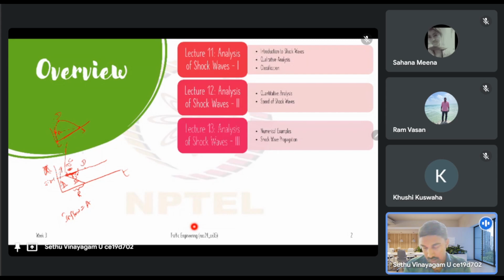So you will have D. So again there will be a boundary that will be found between C and D, right? So that is somewhere there, and then there will be a boundary between B and D. So that is here. That is again negative, but it is at a higher slope. So that is your backward recovery shock wave, right?